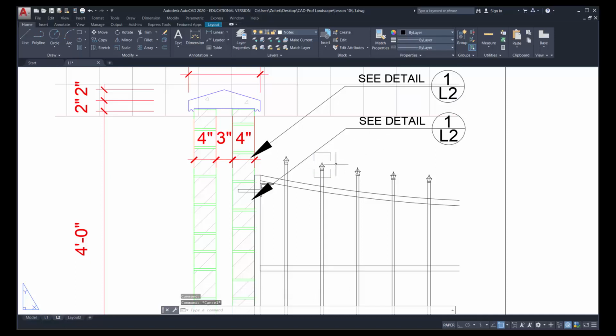Now you notice that the hidden lines are in two directions but not in the other two. That's because this line is too short. And that's what happens with line types. If I stretch this box out a bit, I'll press F8 to make sure it's a nice square box. I have to make sure that this distance is far enough that'll give me that gap.